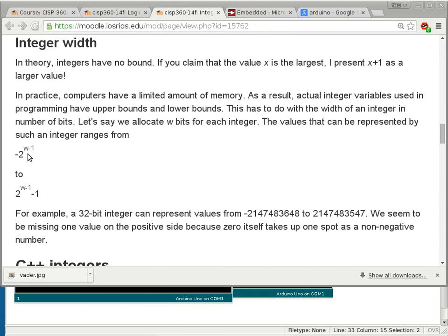Instead of 32-bit, it becomes 16-bit. Some of the arithmetic operations involve integers that require more than 16 bits to represent the values. That's why it runs okay on a regular PC, because on a regular PC an integer is always 32-bit, but when you cross-compile, int, just using int itself as a type, becomes 16-bit, and it was not able to store the value that it needed to store.